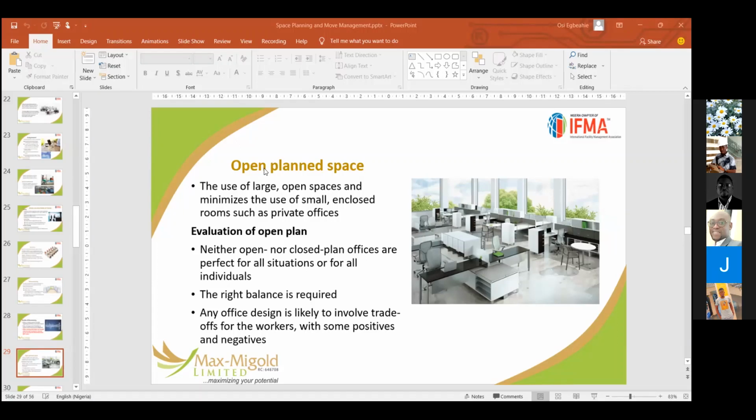You can have as much as 10 people working in an open space than when you break it into small offices. And when you break it into small offices, you tend to spend more to run the office because for each of those individual offices, you may need to provide an air conditioning system to cool them. If you have 5 different offices, you have 5 different split unit air conditioning systems, and that will also impact the electricity cost because you'll be consuming more energy running those systems.